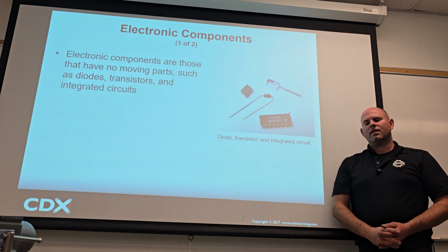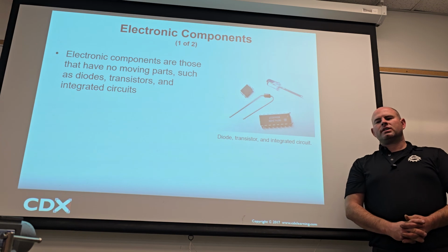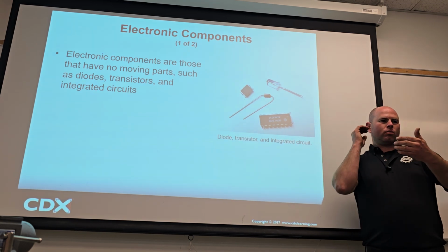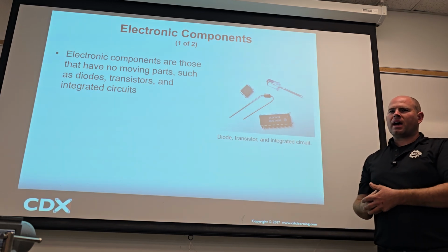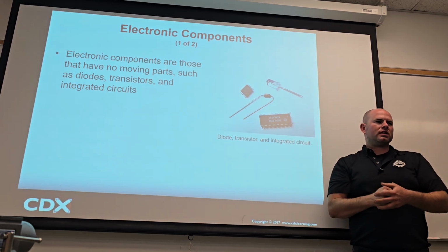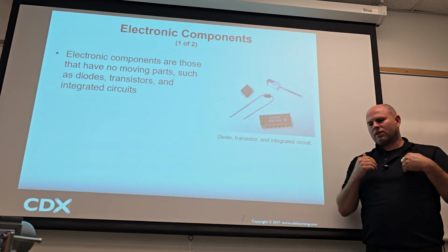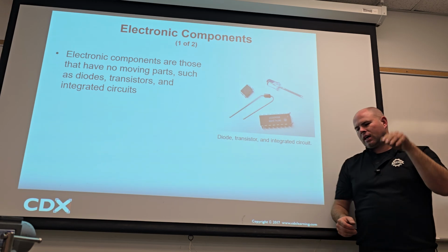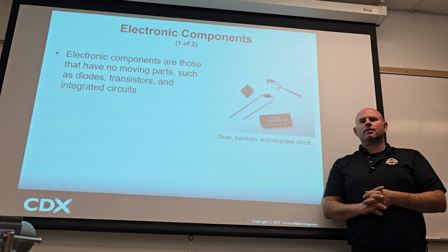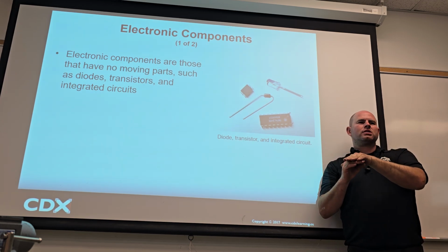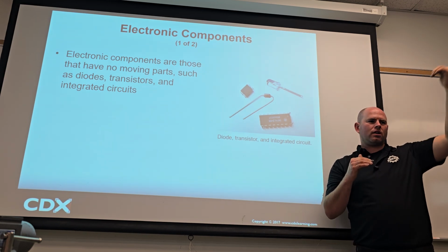Yeah, cool. And from firsthand experience, we've seen a number of times where the crank sensor won't give a signal, and you're like, oh, it needs a new sensor, right? So let's just say backyard style, you slam a new sensor in there. If that new sensor doesn't fix it, that's when you bring it to the actual technician. So some of the stuff that's come to me, I'll check for 12 volts, and I'm getting no 12 volts to the sensor. It was never the sensor. If it's getting no 12 volts to the sensor, that's a problem. Now I need to figure out why it's getting no 12 volts. It could just be a wire in the harness.